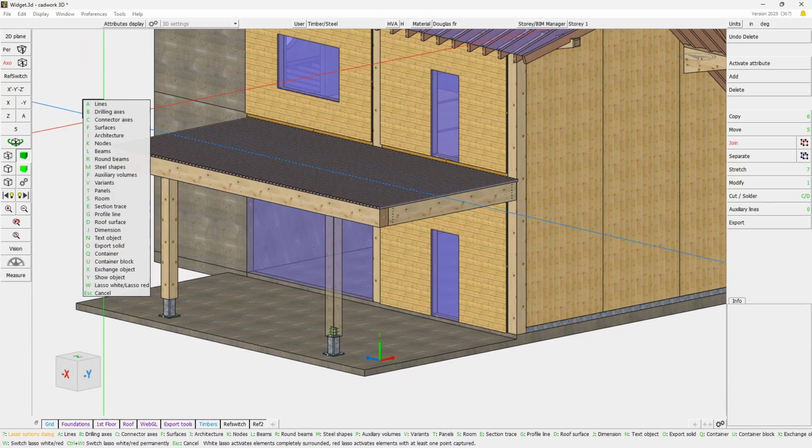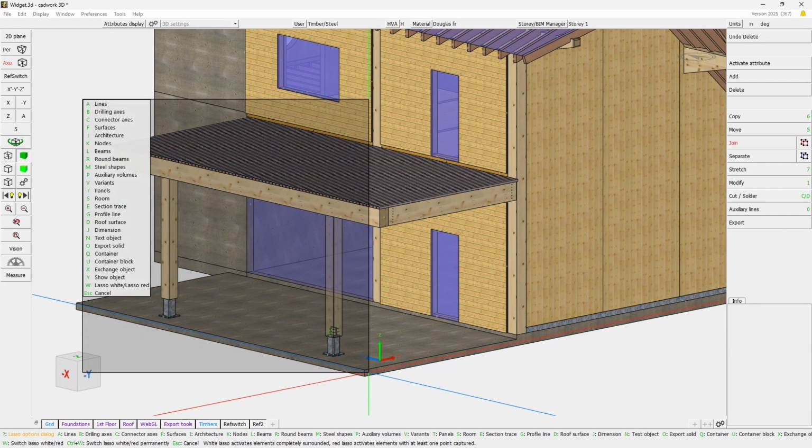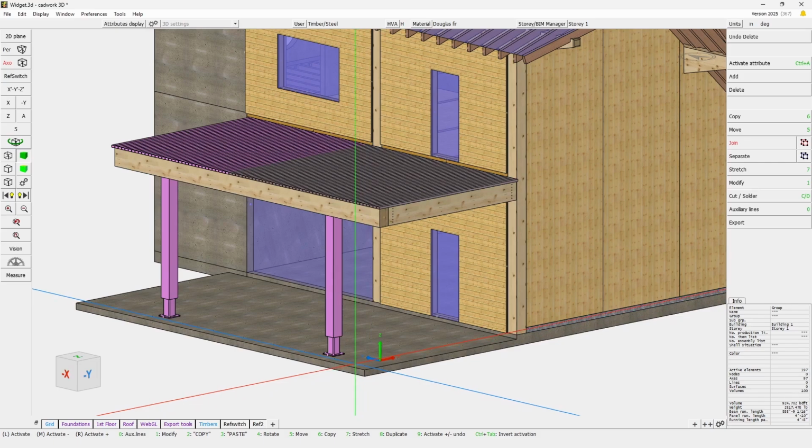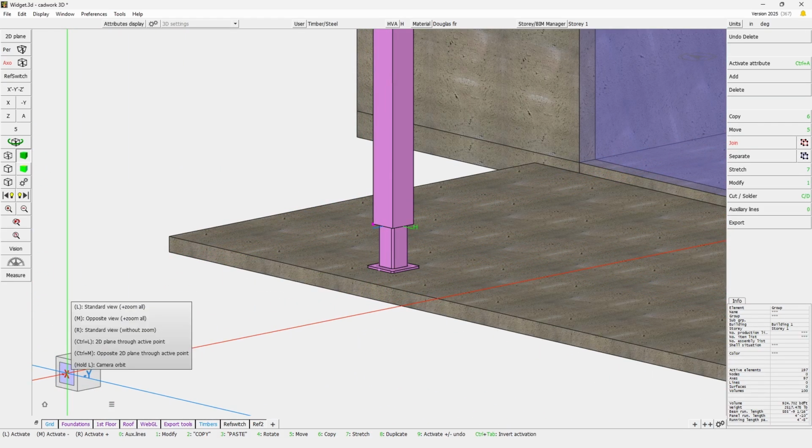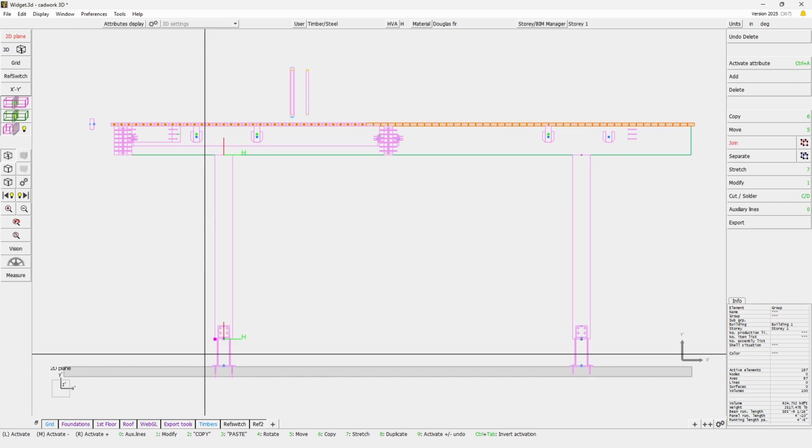And the other thing that this is where it's really useful is when you select with lasso. Because with lasso, there is no first left click. So there is no active point on that current selection. So when working with lasso, it will be important for you to keep in mind this option. So like this, you can easily place an active point and then do whatever you want afterwards.